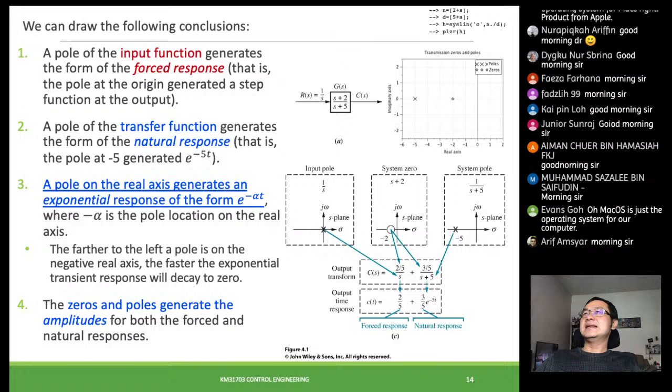I don't draw it, I just show this generated S-plane. But later on, when you are dealing with exams, or when you want to write by hand, then you should always plot like this: just two axes, with sigma to represent the real axis, and j omega to represent the imaginary axis. Just two axes, and then you plot it out, right?